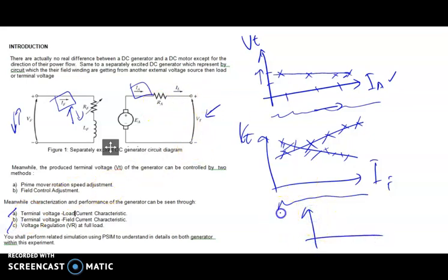So VR means terminal voltage versus what? It should be versus load. You can calculate up front what the theoretical graph should be. Then when we plot, we shall compare between the experiment and our theory.